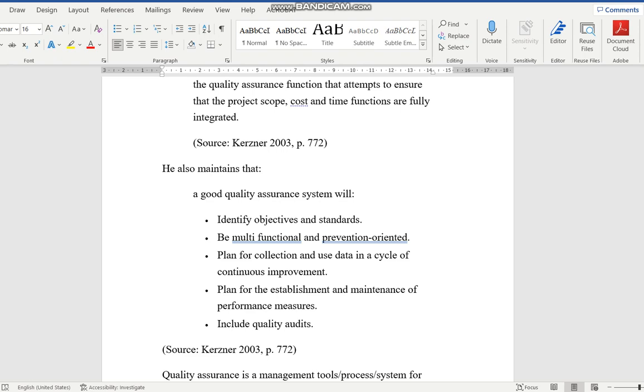Is there any time limit to it? And when you pump it out, do you need to do quick tests? So you add in quick tests, you add in slump tests, and why these types of tests are done. And then you also need to put in the certification, the mix formulation, for approvals.